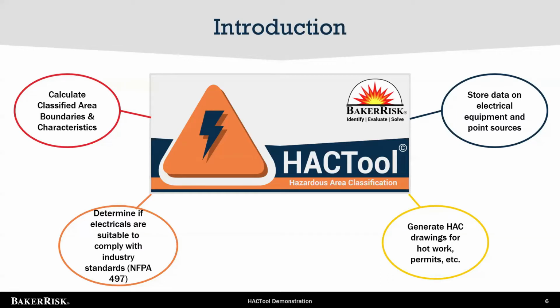And so if you're organized or not, HACTool helps in that process of organizing and storing a large amount of process information and process equipment, maybe where pumps are located, where heat exchangers are located, and some of the temperatures and pressures surrounding that equipment, such that you need that input to calculate the classified area boundaries, at least if you're using NFPA 497, as well as all the electrical equipment in the fields that could pose an ignition source at the end of the day, right? So that's all vital information to know and to store in HACTool if you choose to use it for that purpose.